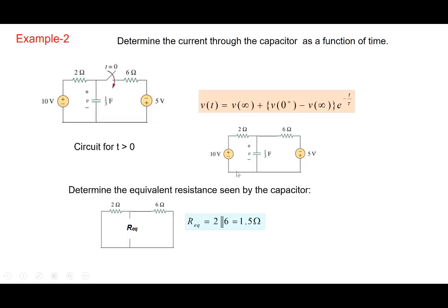Now we could do that, the simplified form, remember when we did Thevenin's and Norton's equivalent, because there are no dependent sources. If there had been some dependent sources, then the determination of R equivalent, which is nothing but Thevenin's resistance, would differ. So what you could have done is remove the capacitor here and found out the open circuit voltage here, and you could have found out the short circuit current here. So opening it, you could have found VOC, and then shorting it, you could have found the short circuit current. All right, so you could have done that.